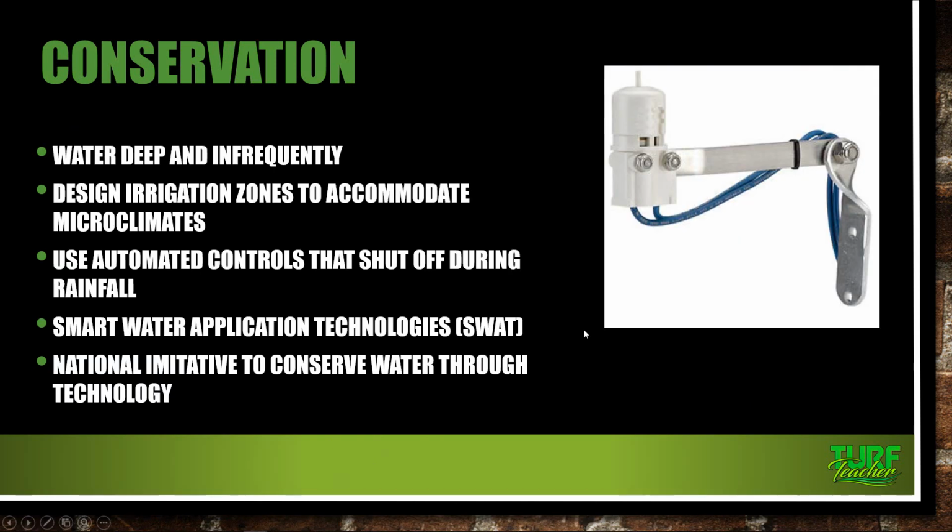Water deep and infrequently. Design irrigation zones to accommodate the microclimates. Use automated controllers that shut off during rainfall. The rain sensor here, guys. Smart Water Application Technologies, or SWAT. And then there is a national incentive to conserve water through technology.